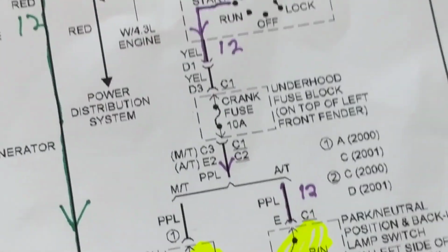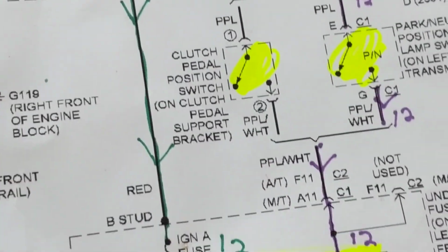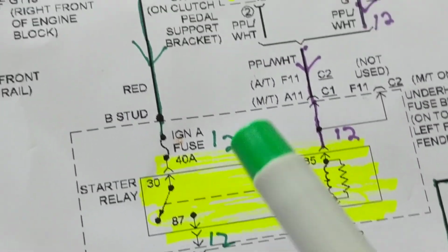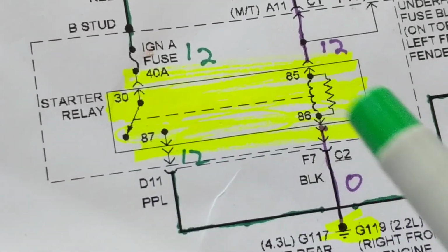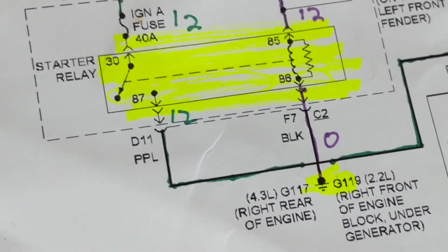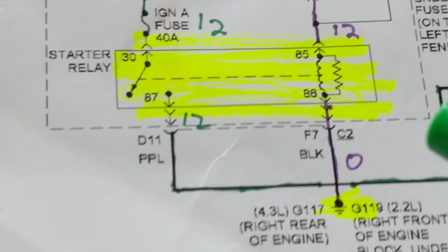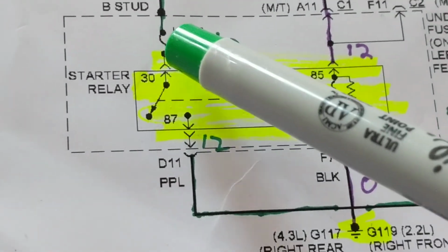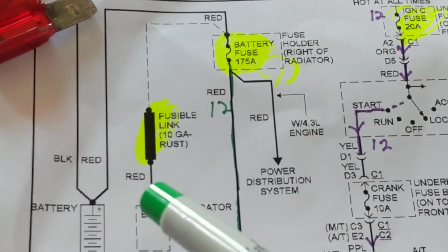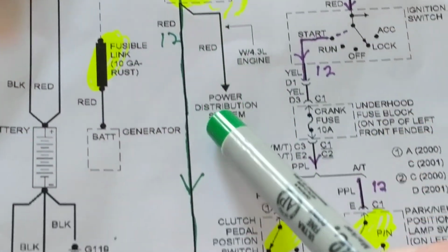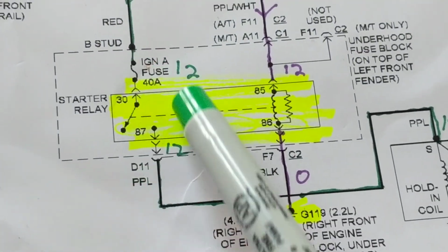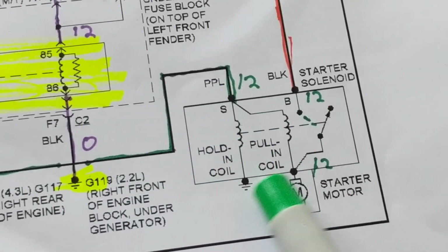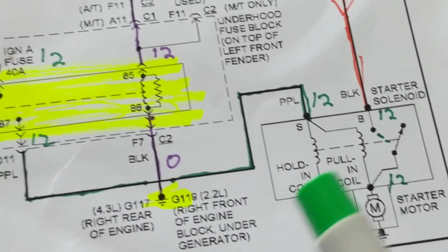But anyway, getting back to switches and grounds, we discussed. There's another fuse rated at 40 amps. Relay. According to the comment I got, if I have a problem with the relay, I go to 30 and 87 and I just jump it. Well, what is this going to? We discussed this one time. We go over here, 12 goes to the motor and the starter. So the starter will go on.